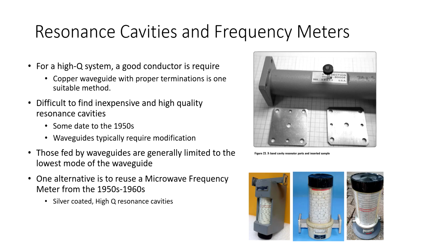All right. So resonant cavities, again, in the lovely publication from Keysight, Agilent, HP, it shows their resonant cavity method. They essentially attach a waveguide and create a cavity, and then you measure S21 through the cavity. You put tiny coupling holes on the end to achieve the resonance within the cavity, and then you throw a little hole in the center and you put your sample down through the hole to measure how it impacts the resonance of the chamber. Beautiful method.